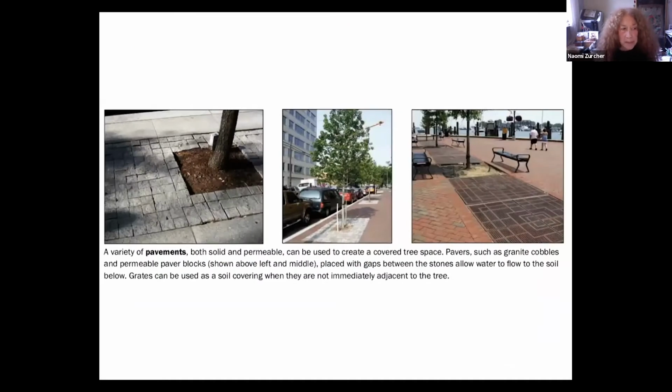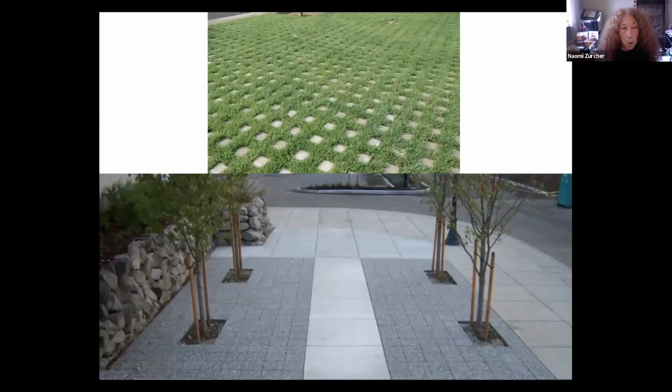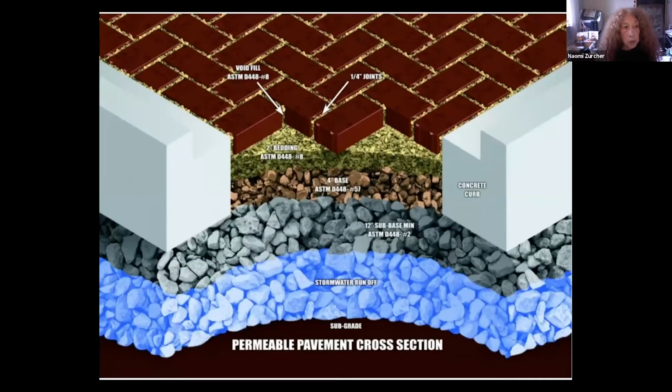The 3 Ps: porous, pervious, and permeable pavers that facilitate water resource management. Porous above and pervious below allow water filtration through the paver, while permeable pavers direct the water into joints that surround each otherwise impermeable paver, delivering a lesser amount of water infiltration than the other 2 options.